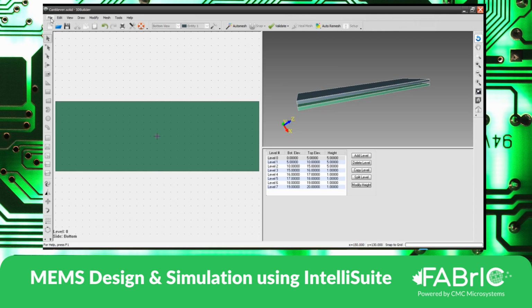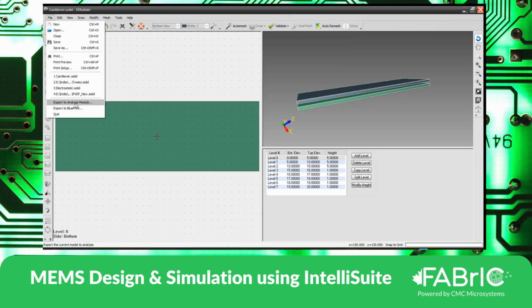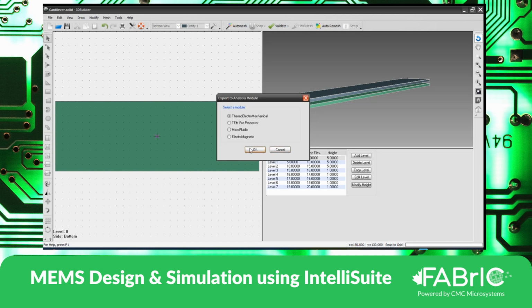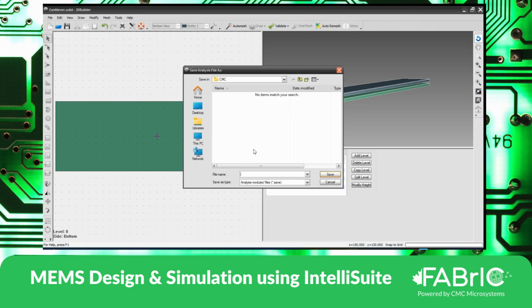Yes. So I have saved this file and let me push this off. I need to check the mesh conformity and connectivity and then click check. And then the software doesn't know what type of simulation you're trying to do. So based on what we are trying to do, we choose thermal electromechanical and then click OK. And it will prompt me to save the file.